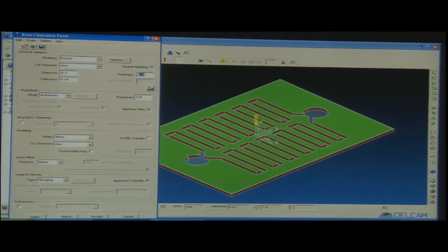So, when there is repetition of certain pockets, the software by itself will pick whether they are pockets or not. We can check it or uncheck it. So, it can machine area by area, pocket by pocket. There are certain ways to do machining. Thickness can be put here. Whenever pocket machining is needed, the software is intelligent enough to identify that the pockets are there.